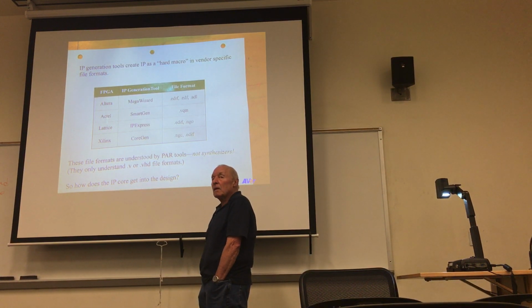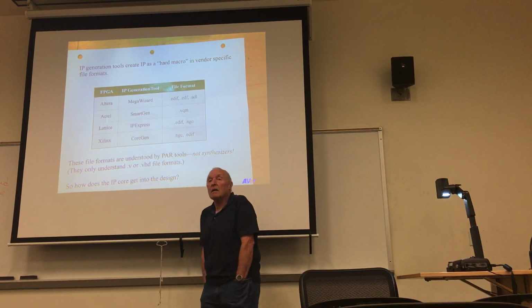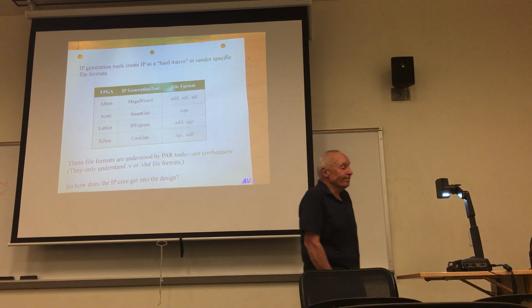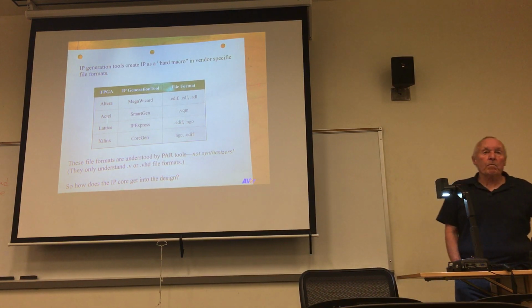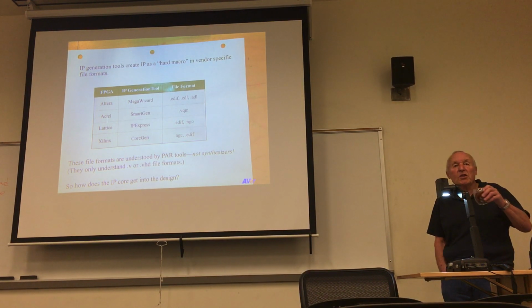Yeah. So I guess I'm a little confused. So those file types that are listed up there are the outputs of core generation, and those are basically also the outputs of the synthesizer. Those file types are the synthesizer outputs. Is that... No. They're generating what a synthesizer would have generated, but it's a netlist file. Right. Okay?